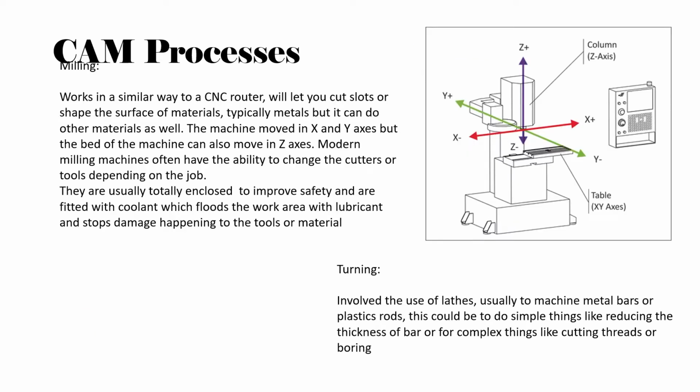Then you've got CNC milling. Same sort of thing: you'll have your file and you'll send it coordinates. I know I was right the first time when I said X, Y, and Z. It works in the same sort of way: your work will be clamped into the machine, like a bench there, and then the cutter itself doesn't move. What happens is the bed, much like the normal mill, the cutter stays still but just spins. And then the bed that's holding the piece is the thing that actually moves. So Z up and down, Y forwards and backwards, and X left to right.